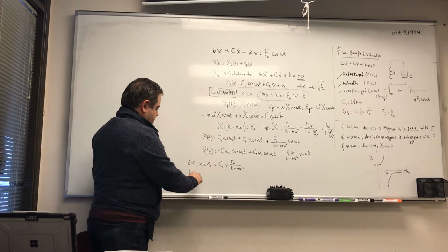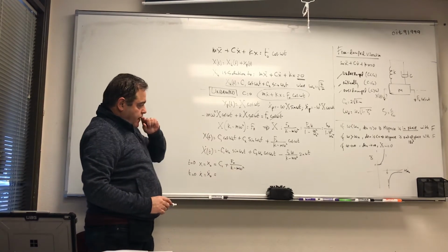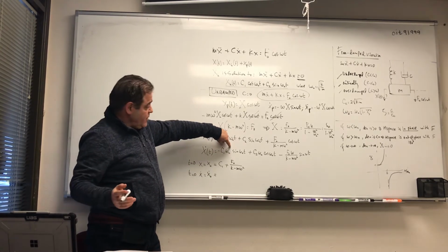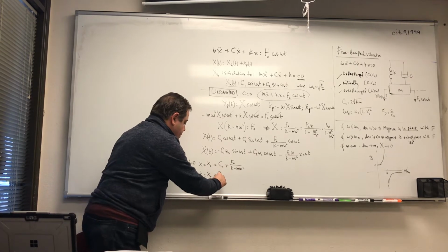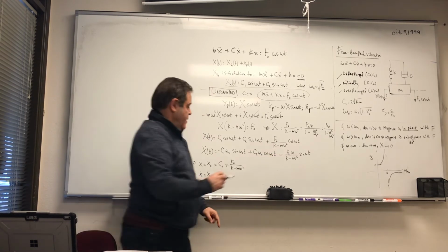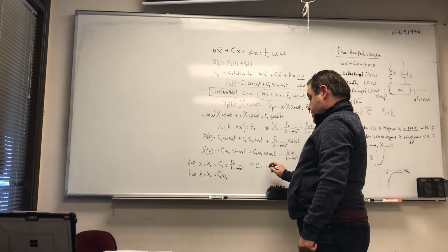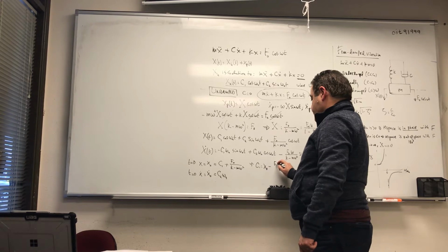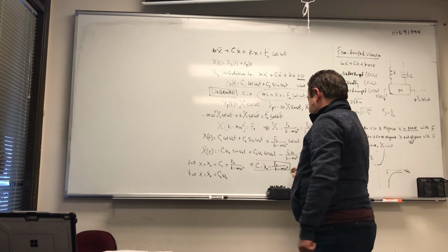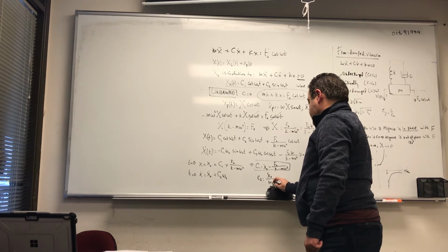At t equal to 0, x dot is equal to x dot 0. Come back now to this equation. The first term, no contribution. Second term would be C2 omega n cosine 0, which is 1, and this one, no contribution. So from this equation here, I can figure out what my C1 is, which is x naught minus F0 over K minus M omega squared. And then C2 is simply equal to x dot 0 divided by omega n.